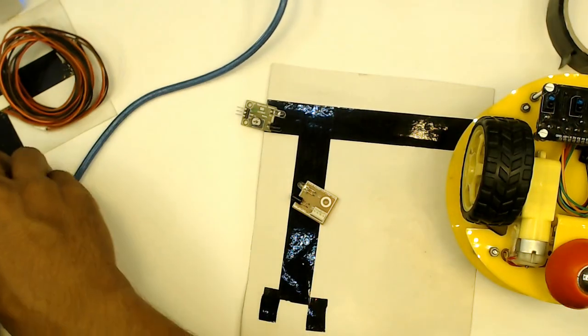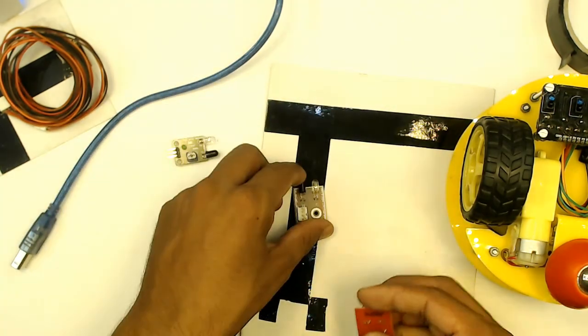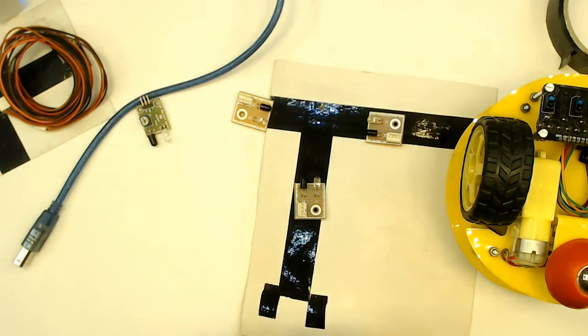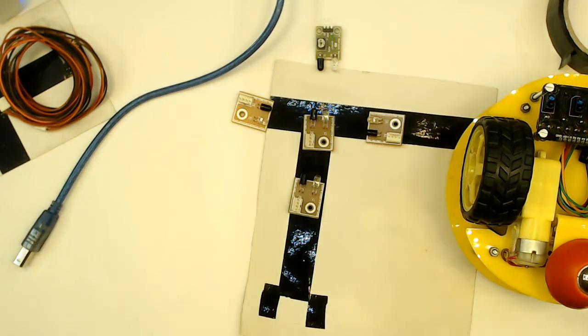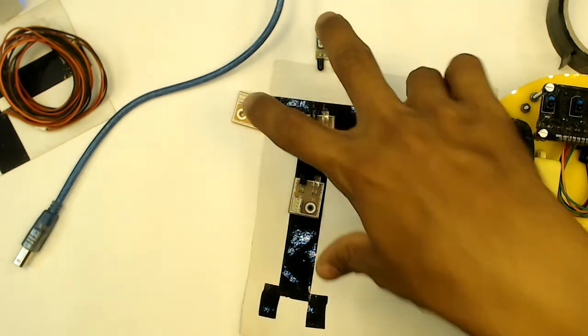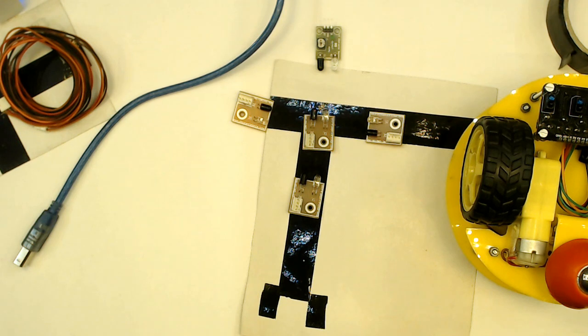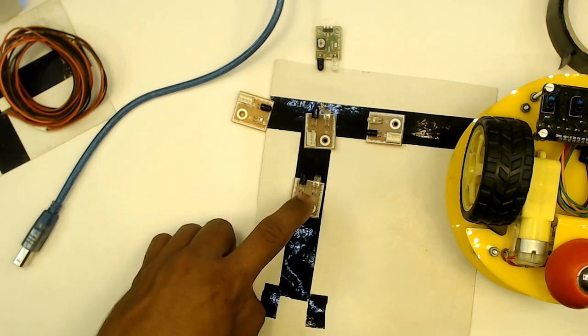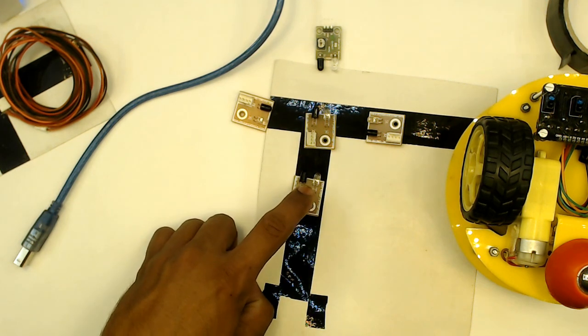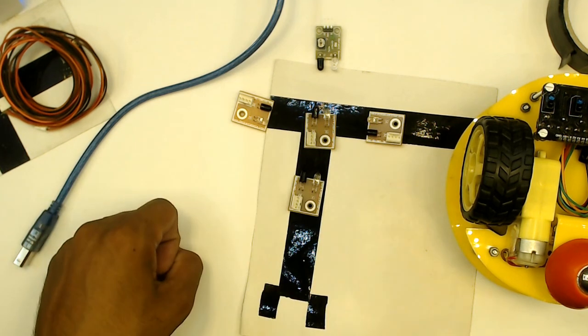The pattern which I generally prefer is this. I would have preferred having the sensors in this pattern. So it's a cross pattern. Whenever, at any given moment, you're scanning this sensor pattern, you will very easily be able to identify: if I'm getting the left sensor, center sensor, and the bottom sensor on, it means that I have a left section.